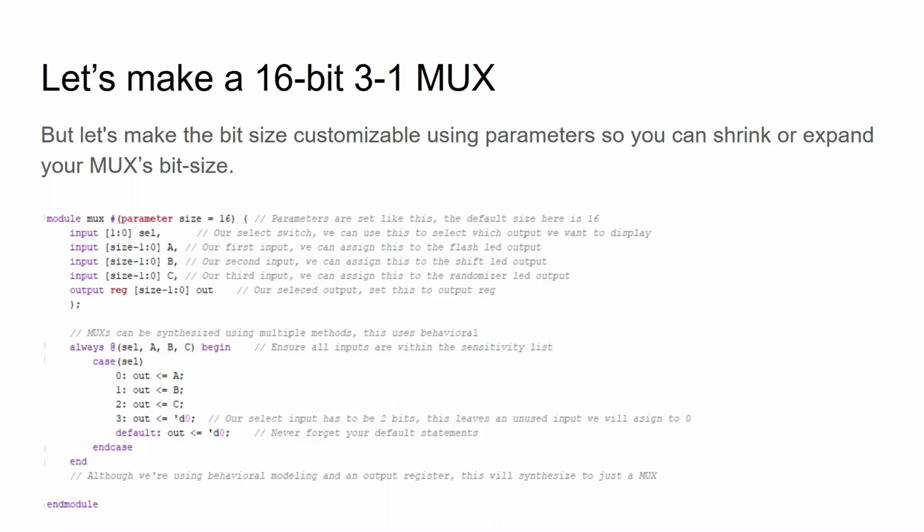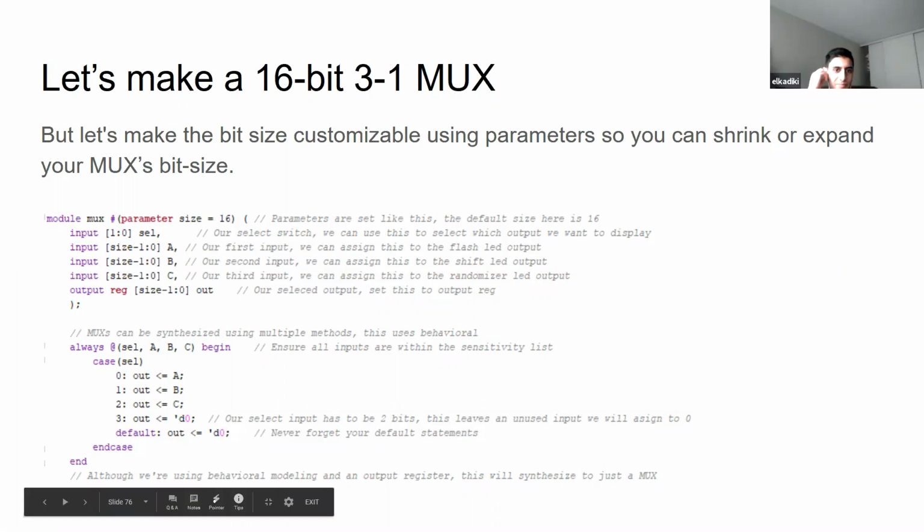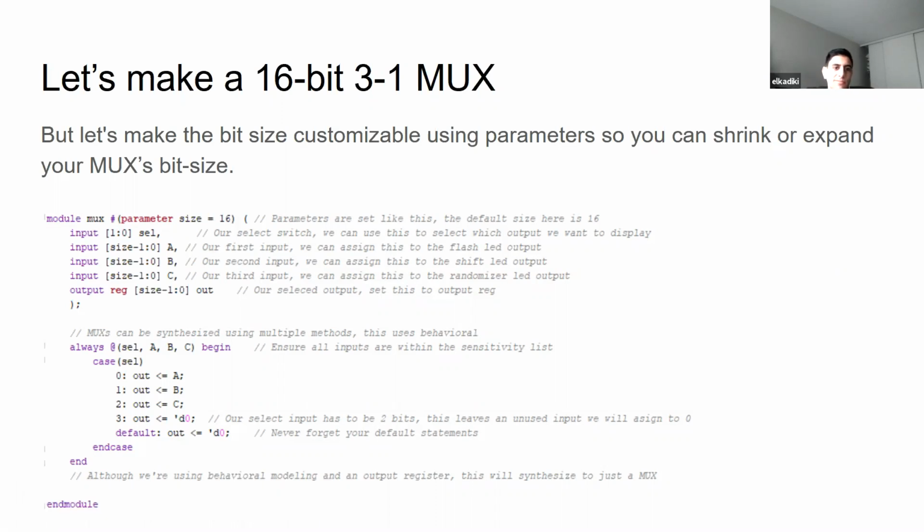Sorry, do you mind repeating that? When would that happen? Vivado will do one of 2 things if your code isn't correct or there's something weird. It'll either silently delete 90% of your design, putting it as minor warnings. It'll synthesize, generate a bitstream, and then you put it in the board and it does nothing because Vivado decided none of this is going to work, so it deleted it.